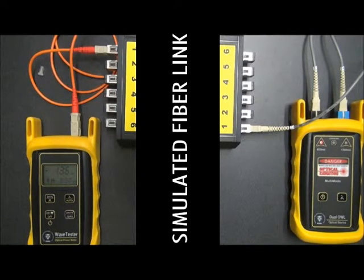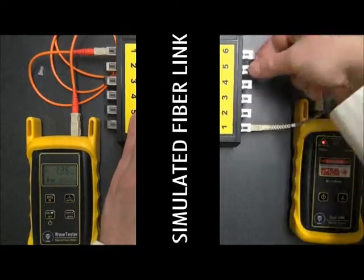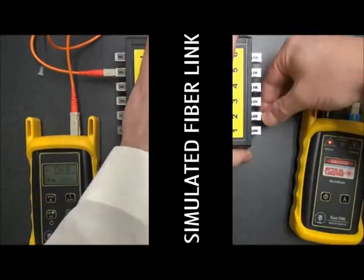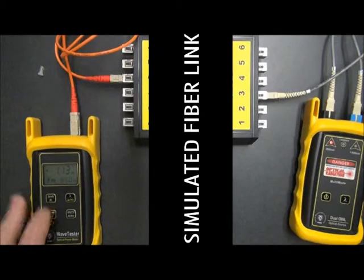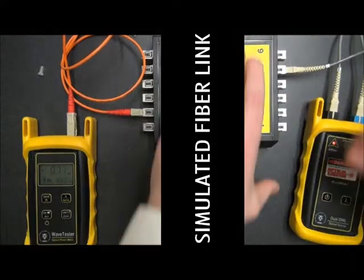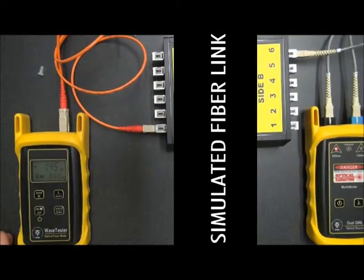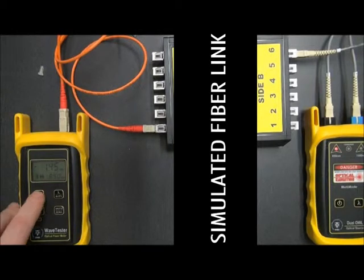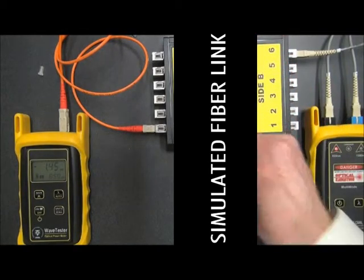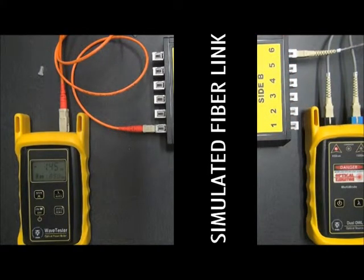And what I'm going to do is speed that up here now. And finally, we store a reading for fiber number 6. Now, as you can see, the fiber numbers incremented as we store the results. At this point, we have 6 readings stored in the meter. So they correspond with the 6 fibers that we've tested so far. Now, as you can see, we have tested all these fibers at 850 nanometers.